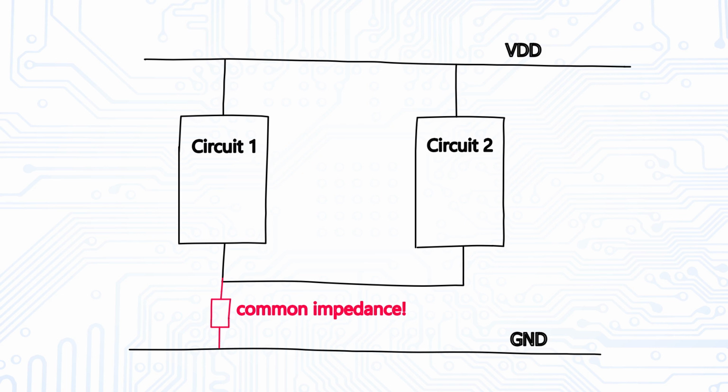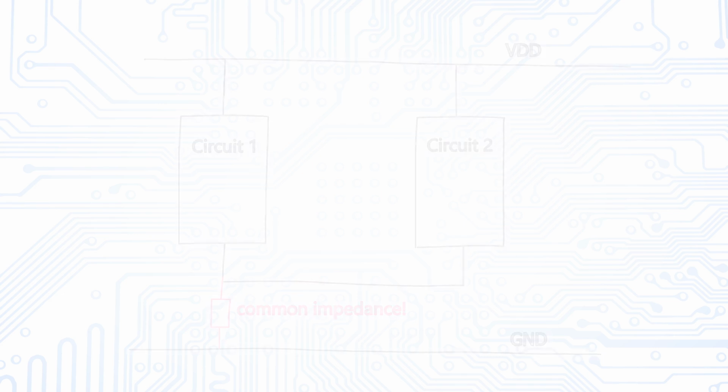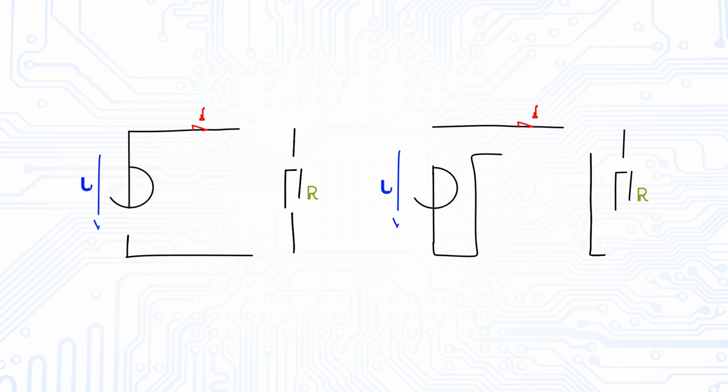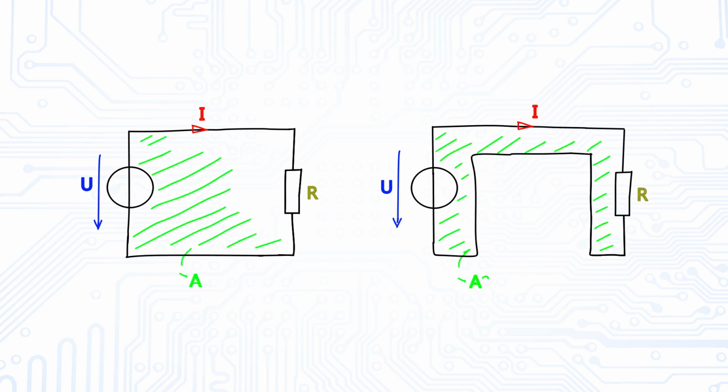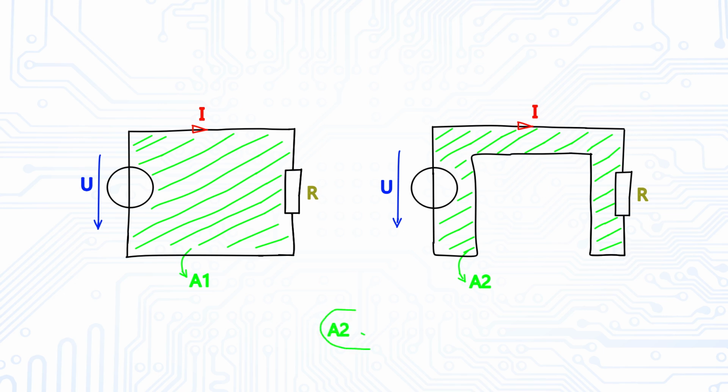So how do we reduce parasitic inductance? This can be achieved by minimizing the loop size within the circuit, as illustrated by comparing the two sketches. The right sketch, depicting a smaller loop area, is optimal for EMC because it not only mitigates galvanic coupling, but also diminishes parasitic inductive coupling.